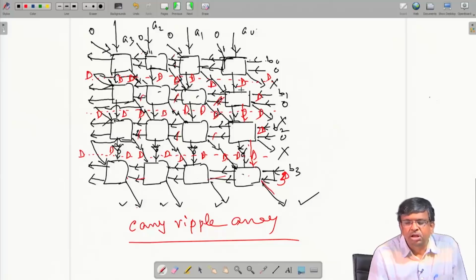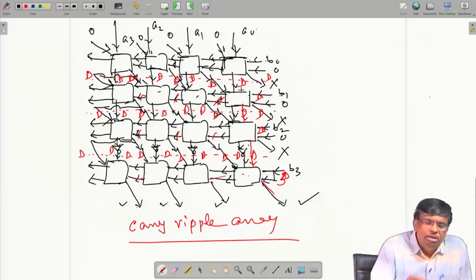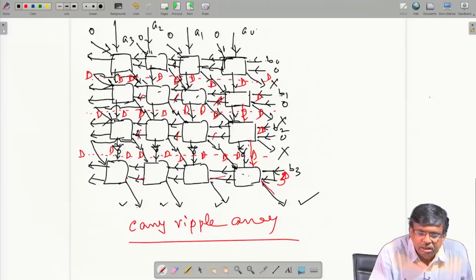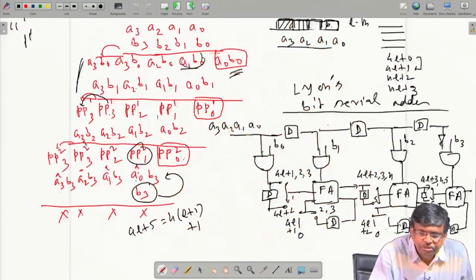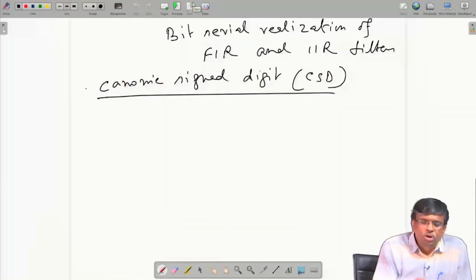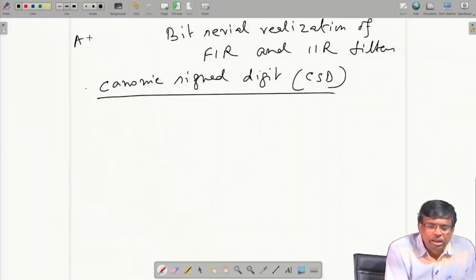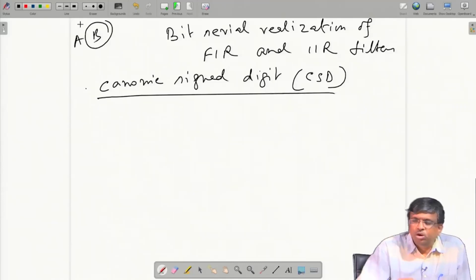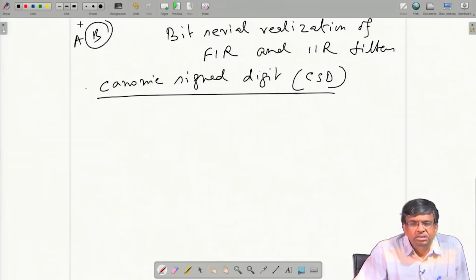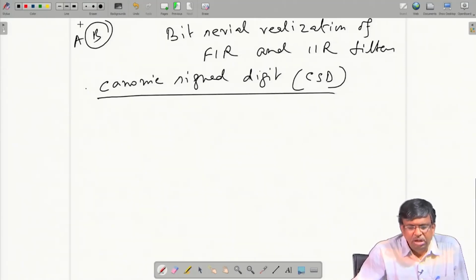So, you get some saving in hardware, which means if it is like this, that out of two numbers you are multiplying, A and B, at least one of them has many bits equal to binary 0, then your multiplication complexity will go down hugely, because many rows in the overall multiplication table by Horner's rule will not be required, because you already know the result.